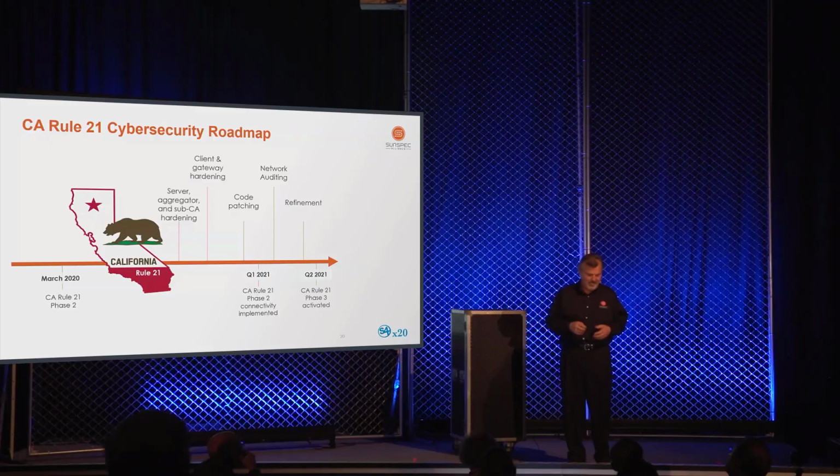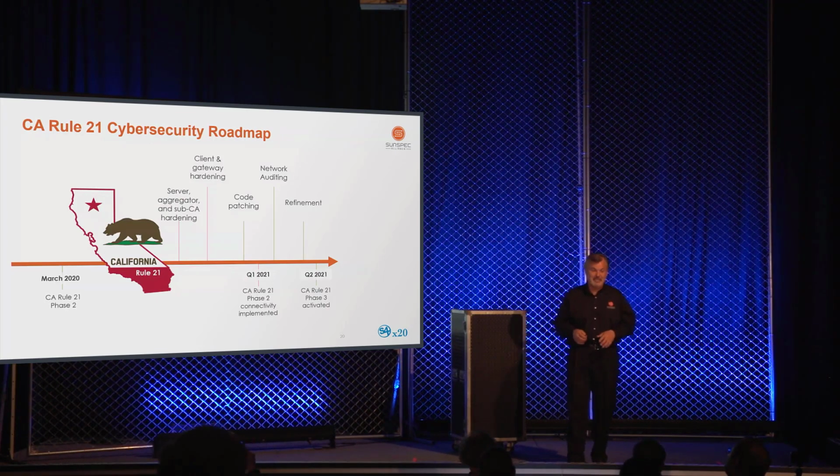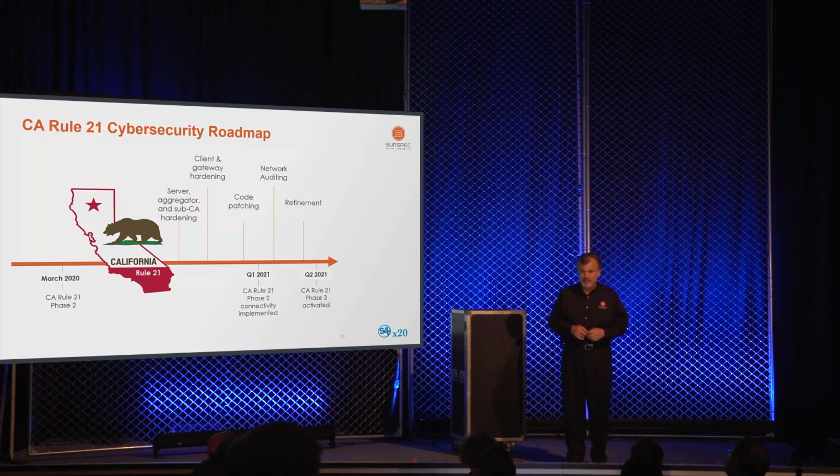Secondly, about the 61850 versus the Modbus question. We started SunSpec 10 years ago. The reason was we were having to deal with all these device drivers for inverters. And we thought, oh my God, what can we do to get rid of this Modbus stuff? And 10 years later, we're saying, oh my God, what can we do to get rid of this Modbus stuff? And it's not going away. It's supported everywhere, because it's simple and it doesn't break.